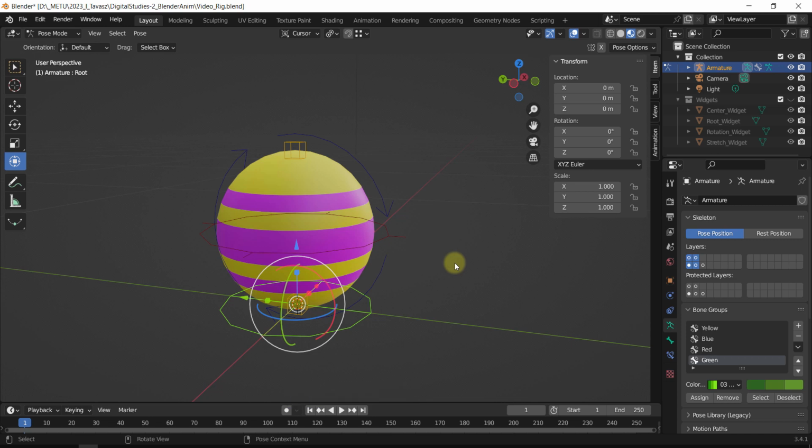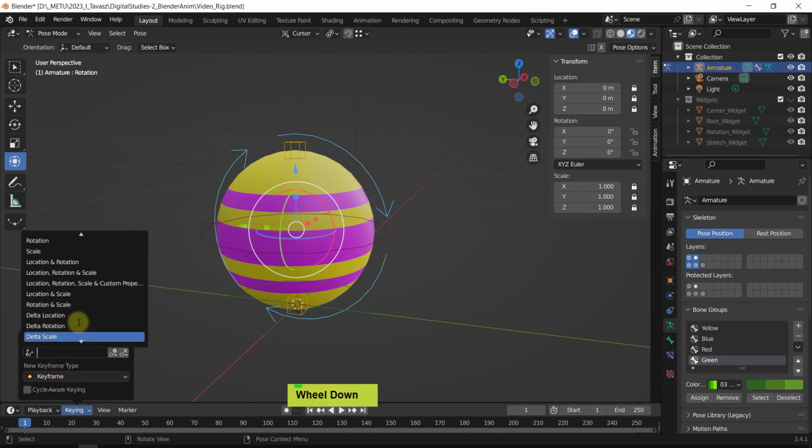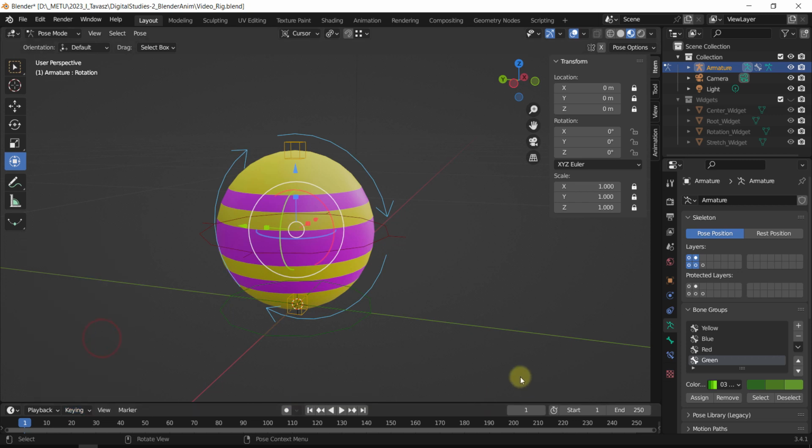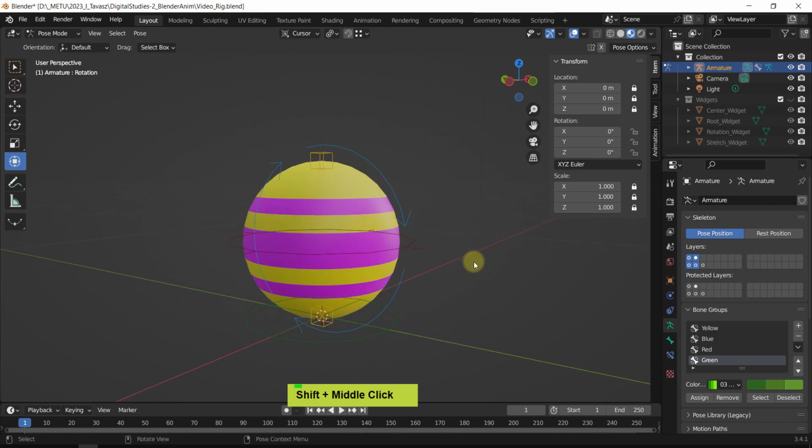And before animation, what we will do is adjust the keying type. Because we have locks involved, the keying is going from the active keying set. Just walk down to the very bottom, the whole character, and selected bones only. So those will help us with the auto key process. All right, so the next part, how this auto key process is working.